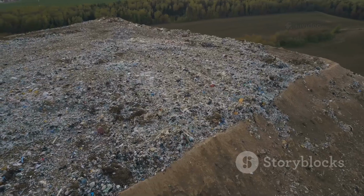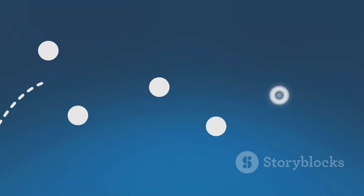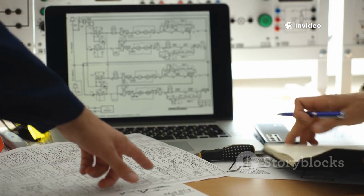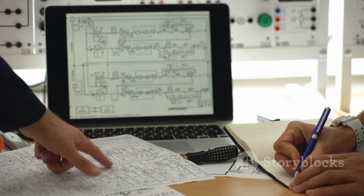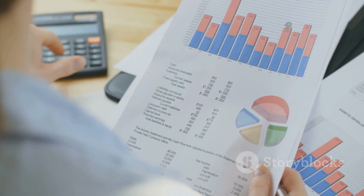The peaks are where you have extra dirt, the valleys are where you need it. A loop that starts and ends at zero means a balanced section. No dirt wasted, no extra needed. The diagram is full of these loops, and engineers use them to plan the most efficient movement of material. It's like a financial ledger for dirt, showing surpluses and deficits.